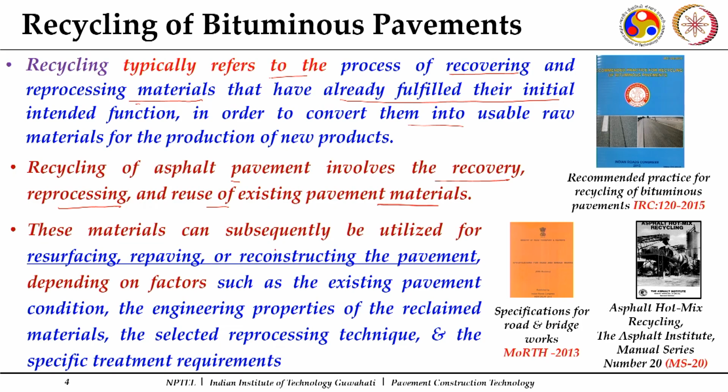These recycled materials which we produce can be used for resurfacing. For example, an existing surface showing extensive signs of distresses can be reprocessed, and again laid as a new surface layer with that material. So, it can be used for resurfacing, repaving, putting up some new layers using that material, or reconstructing the pavement when we go for a greater depth.